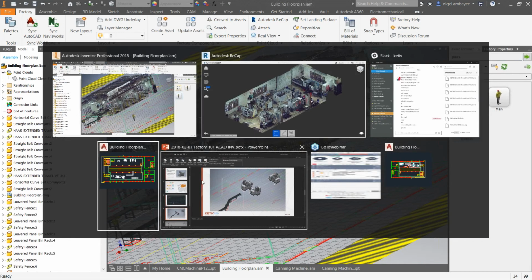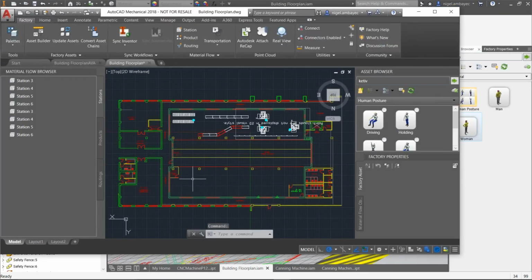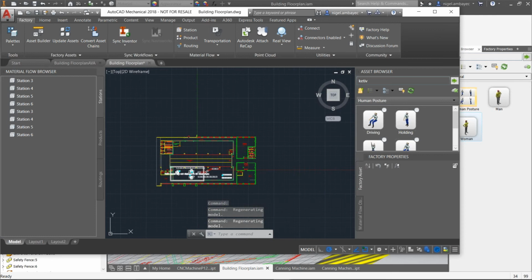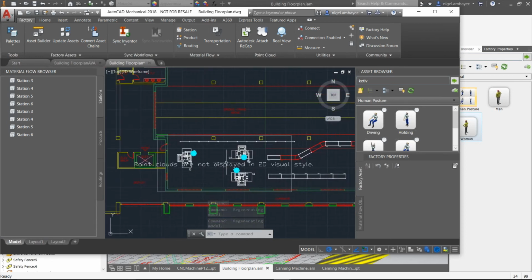and it opens AutoCAD. If the file's already open in AutoCAD, it doesn't work. You have to make sure that the file's closed in memory on AutoCAD so it can open a fresh copy, because it'll say, hey, this file's being used in AutoCAD. Please close this. I'm sure a lot of people have seen that when you're trying to eject USB drives. It says, hey, this file is in use, or a file in this folder is in use. Please close it before you eject this. It's the same kind of case here.